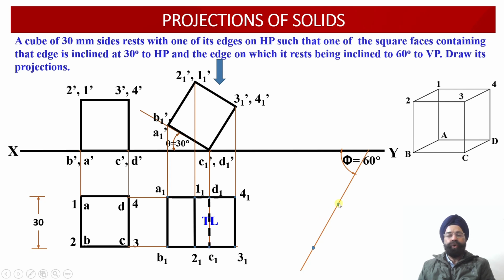So what we can do is, from this point and from this point, we have to draw two perpendicular projection lines or construction lines over here. The moment we mark these two construction lines perpendicular to C1, D1, they will be appearing as C2, D2 over here. Now we know the rectilinear distances between D1 and 4, 1, the distance between D1 and 1, 1, the distance between D1 and A1 over here.